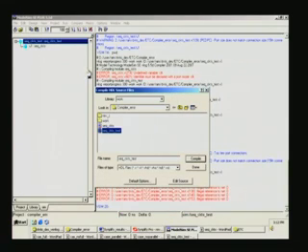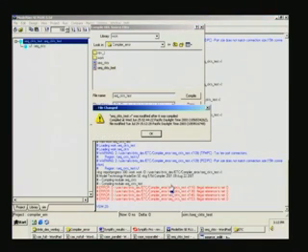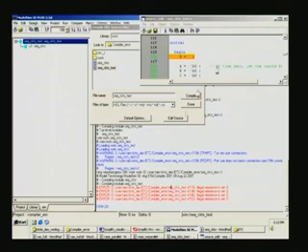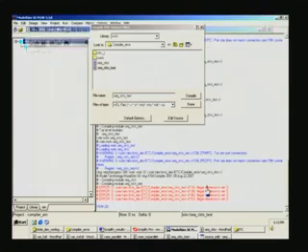So, ModelSim is reporting error here. What it says is illegal reference to net. If you double click, the source will open. So, where did we change? We have changed for D. This was supposed to be reg, but we deliberately made it wire. So, it is promptly reporting here, right. All of them are with reference to D at various points of reference. At 4 places it has been called.